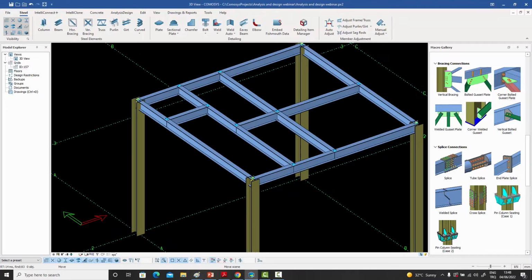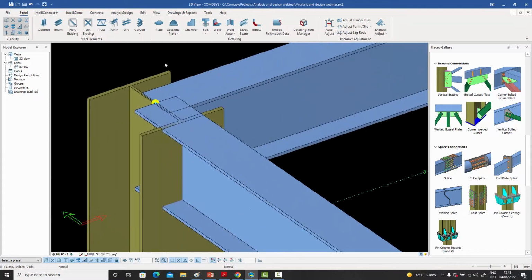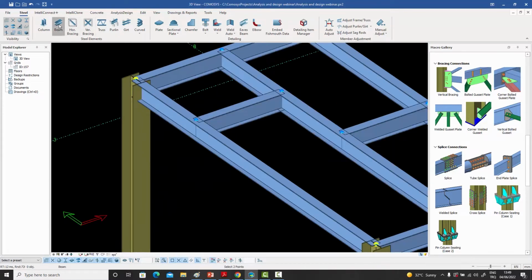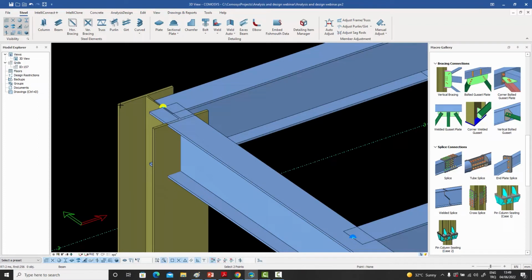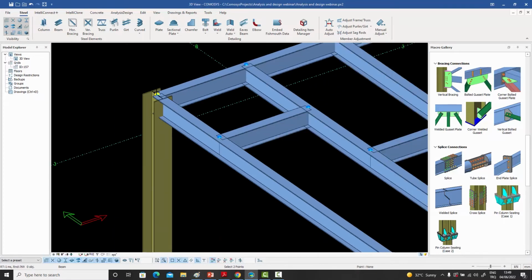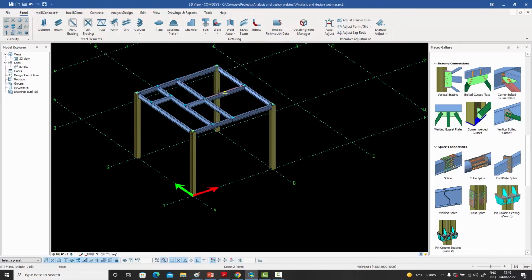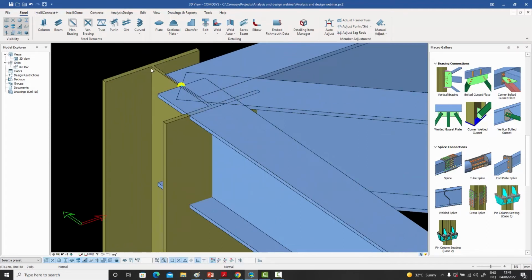Now, one thing which I want to say is that if I zoom in there, for example, and I wanted to enter a plate, just like you can see that I can snap to any one of these points like that. All those are snappable points. But if I were to enter a beam, it doesn't snap to those points, because it wants me to snap to the finite element endpoints. I could be working from this zoom level, and I could just go in there and say, okay, I want an element from there to there, and accidentally I could have chosen maybe this point when I was doing that.